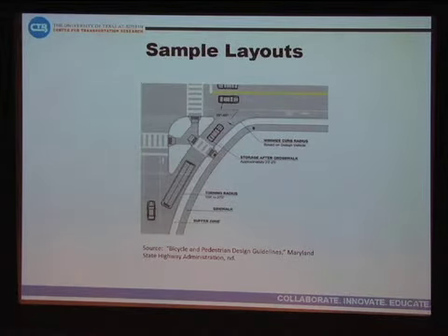That's motivated some of the designs implemented by other agencies around the country. This is from the Maryland State Highway Administration, where they've implemented more of a sharper angle with the cross street. As you can see there, they've also implemented the longitudinal pavement markings for all crossings here. You see the compound curb radius for the turn to help facilitate the turning radius of the larger vehicles. We have movement of the crossing towards the middle of the channelizing island, which allows for some storage space downstream of the crossing for smaller vehicles.